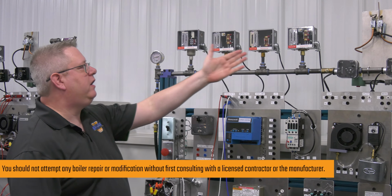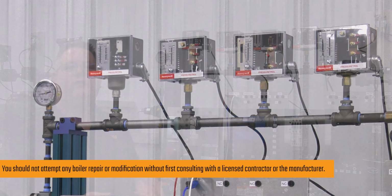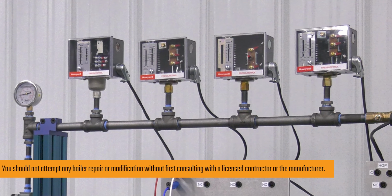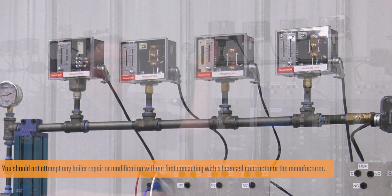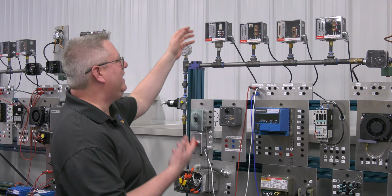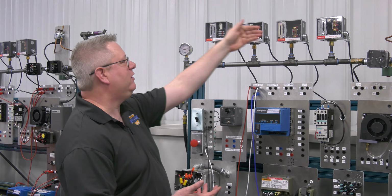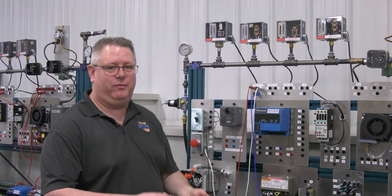We're taking a look at our pressure controls on our steam boilers, and one of the first questions that I get is how do you identify which switch is which? Because before we go to adjusting any of these, we obviously want to make sure we know which one we're adjusting. The first and easiest to pick out really is either the firing rate control or the high limit, because they're distinctly different from the others.